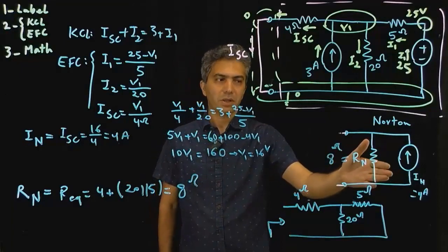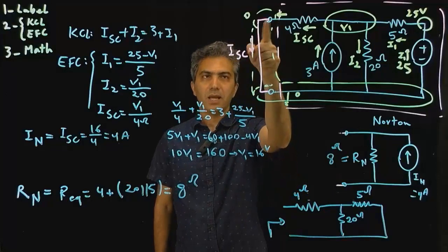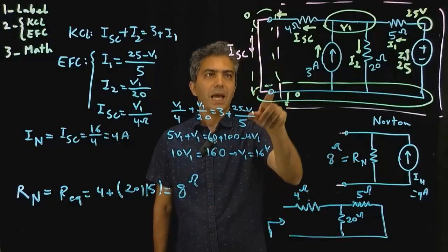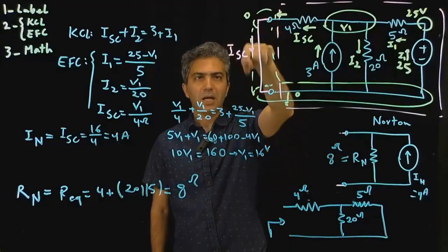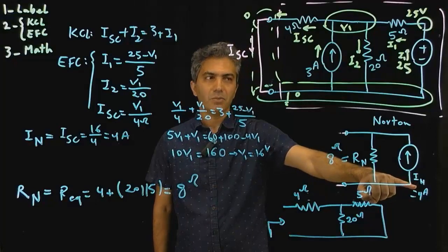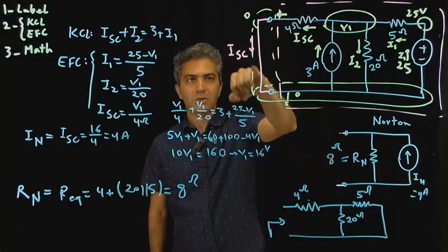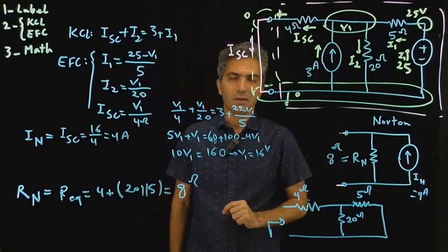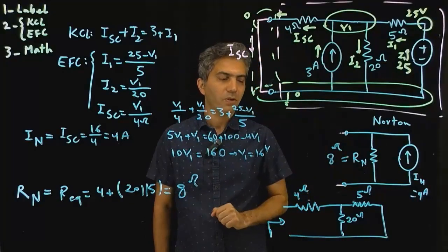With the Norton modeling, you take the 2 terminals and connect them to each other, short circuit the 2, and once you do that, the current that is passing through that short circuit has to be equal to IN. In other words, to calculate IN, you just short circuit that, and that current is the value of IN in this circuit, because these 2 are equivalent to each other.